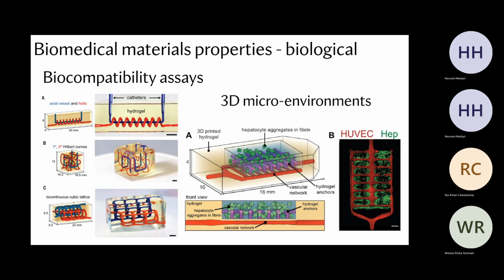Now, in that regime of, let's say, 50% conversion is where we have a good part with structural integrity and it can hold its shape. So we have a range from 50 to 100, okay? Now, if I stop at 50 and then put it in the solvent, the mesh density is going to be much less because I'm removing the monomers, right? If I allow it to go further, 80% through the process, and now I take it out, put it in the solvent, I'm going to have a much denser mesh because it's had more time to cross-link.